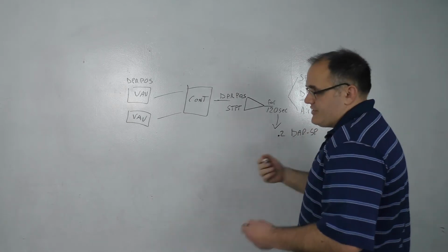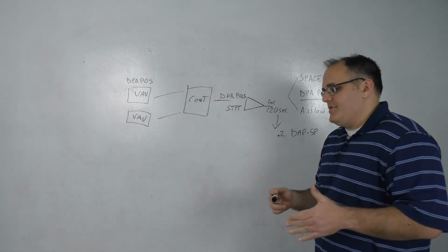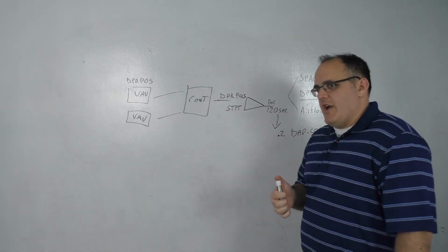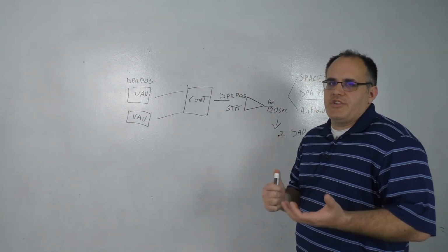And so, whereas our previous strategy with the air handler was focused on resetting temperature, here our strategy is focused on resetting the discharge air pressure set point.